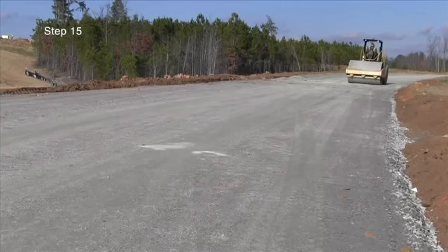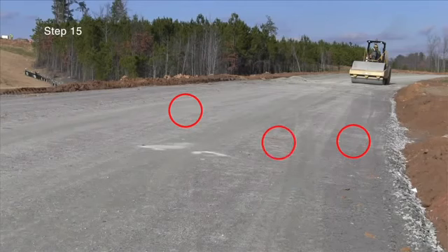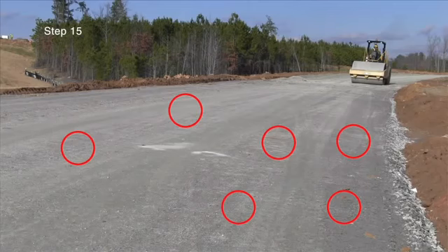As outlined in ASTM D7698, a matrix of 6 spots should be used during the calibration procedure. These spots should consist of 2 different soil density conditions with 3 different water contents for each one, which cover the range anticipated with the specific material.